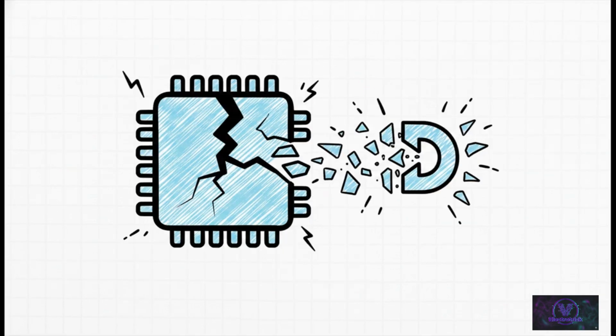And that brings us to the absolutely most critical insight for today. Inrush current is not just a power grid problem where your wires get a little stressed out. No, it is a full-blown functional integrity problem. If that stolen charge causes a significant enough voltage drop, a logic 1 in your active block will degrade. It dips way too low, those logic levels get totally disturbed, and boom, you have an outright functional failure in a part of the chip that was working perfectly just a microsecond ago.